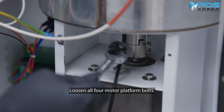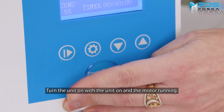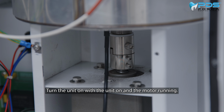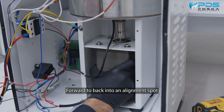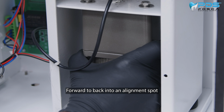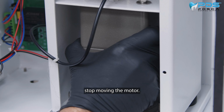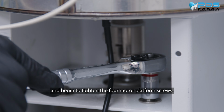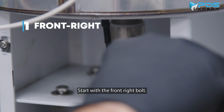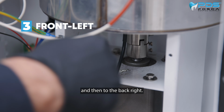Loosen all 4 motor platform bolts. Turn the unit on. With the unit on and the motor running, gently grab the motor and move it from side to side, forward to back, into an alignment spot where the noise stops. Once you hear the noise stop, stop moving the motor, hold in place, and begin to tighten the 4 motor platform screws. Start with the front right bolt, move to the back left, to the front left, and then to the back right.